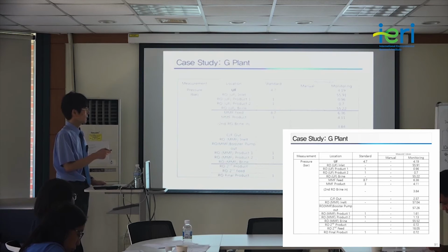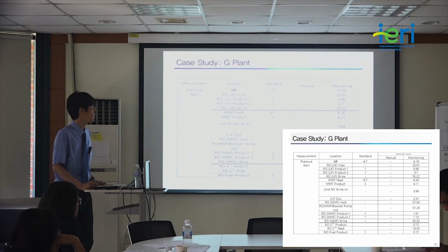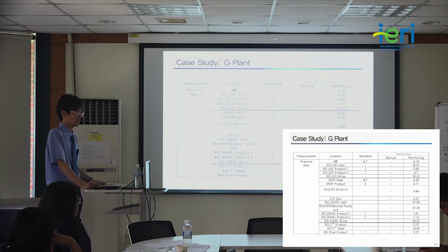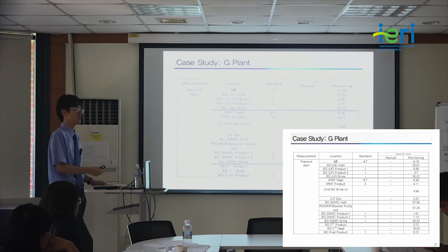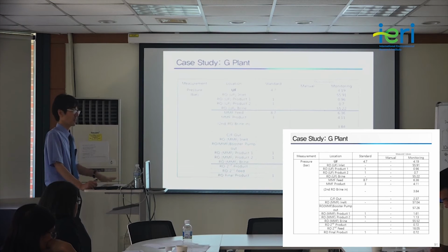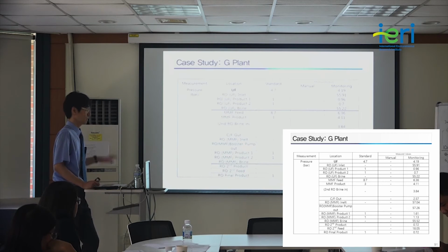So in this case, we require a pressure of 57 bar for the operation of reverse osmosis, and the reason is that this was recorded in December, so the seawater temperature was very low, so more pressure was required to have enough flow rate. So the pressure was slightly higher in this case.